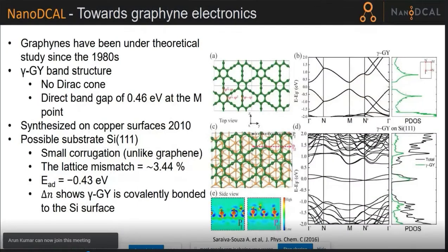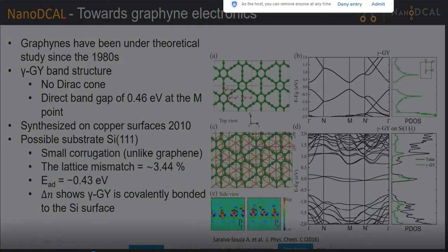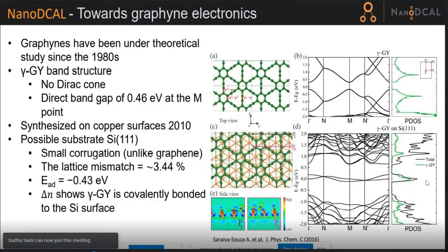This software can also work in graphene electronics applications as well, where you can find the direct band gap, indirect band gap, stability of the structures, Brillouin zone route points, band structures on different positions. You can rotate certain atoms or replace the atom with different other dopings or delete the atoms. So any type of surface, Miller indices, lattice mismatching, adsorptions, bonding, non-bonding, lattice, bond range, bond length you can adjust and manipulate as per your needs. You can find the band structure on different Brillouin zone route points on different surface structures and plot the PDOS and other characteristics.